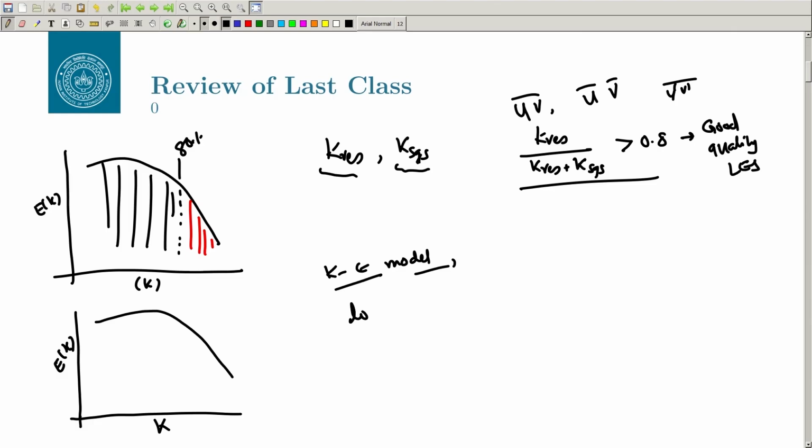And how do you calculate that? Remember, as we discussed for the eddy viscosity models, all these models have this nu turbulent or nu eddy. Eddy viscosity is basically some factor of L naught into U naught, some length scale and some velocity scale, because its unit is meter squared per second, and this is meter and this is meter per second. If you are using a k-epsilon model, then your L naught will be k to the power 3 by 2 by epsilon.